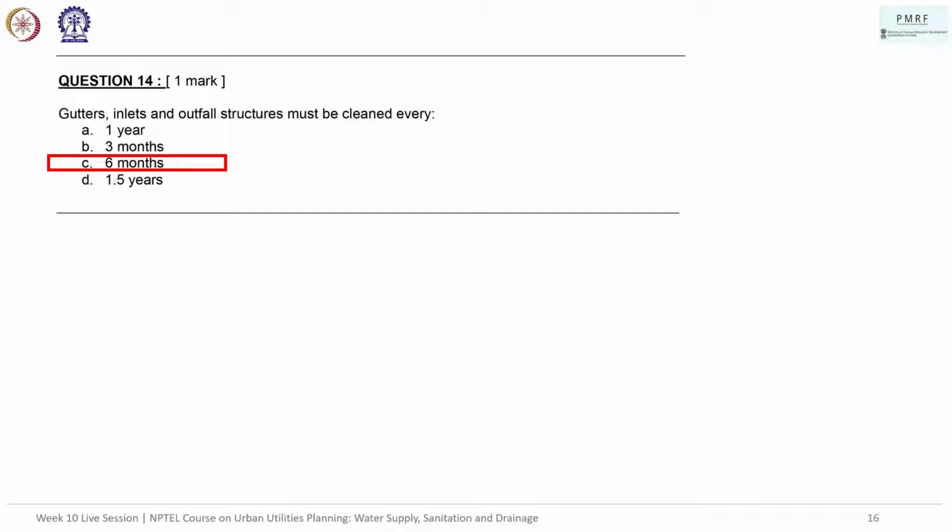So dredging is when you have a stormwater drain or some kind of artificial channel, right? And there is siltation that has happened over the channel that was originally open, like clear. So that's dredging. Excavation is usually a priori. Before construction, you excavate the land and then you construct something. So that's like excavated land is green. It's not really been constructed on before, right? Like it's not been excavated before. Okay? Dredging is just the removal of silt.